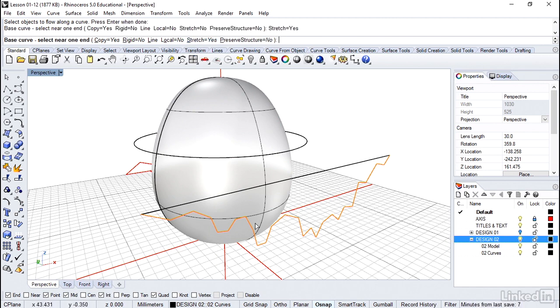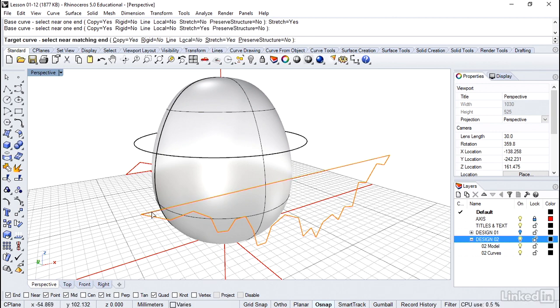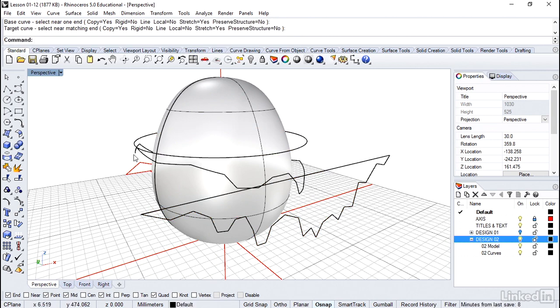If you don't, this line, when flowed, may not wrap around perfectly one time. It may be short, it may be long. So now we can verify that it will exactly hit the beginning and end at this exact same spot every time. It's going to basically stretch to fit. Okay, the base curve is the reference we discussed earlier, that's the straight line. And then for the target curve, we want to pick somewhere near that seam. As soon as I do so, we get instantaneous transform flow.